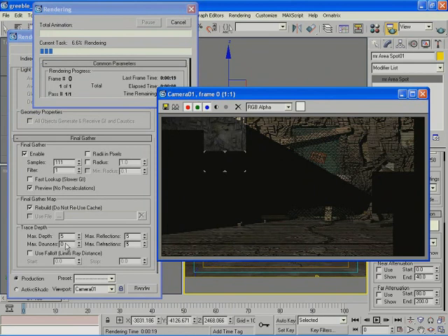So to brighten up the dark areas, which is the occluded areas with the shadows, I would increase the maximum bounces. I'm going to let this render for a while before I increase that. I like what I have so far. What I need to work on is the darkness in the shaded area. And this is accomplished using two things: the skylight and the maximum bounces. I'm going to increase the maximum bounces to 5 and see what I get.